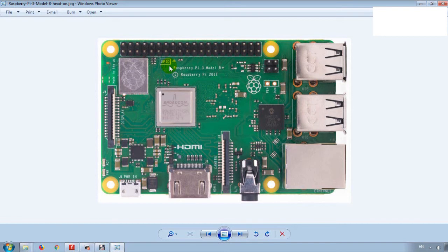and underneath you can see it's written GPIO, which is general purpose input output for the board that we are going to use. One of the most important things you have to know is the number of each pin, because when you want to assign each pin as input or output, or when you want to write something to or read something from these pins, you have to know the number of that specific pin.